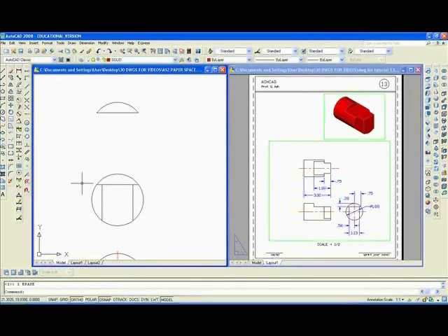Well, there's a lot of ways of doing it. I can trim. Let's say I trim. No, let's say I break first of all. I'm going to break this arc. I'll pick any 2 points. And then I'm going to trim from that line and that line. Enter that and that. And I'm going to trim from this line into this. And I'll erase this. And I'll pan down.